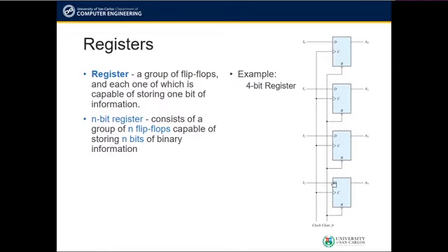The diagram here shows an example of a register. It is a 4-bit register made up of 4 D flip-flops. The circuit is capable of holding or storing 4 bits of information as given by A0, A1, A2, and A3 when specific binary inputs are introduced in I0, I1, I2, and I3 together with the correct clock inputs to each of the 4 flip-flops.